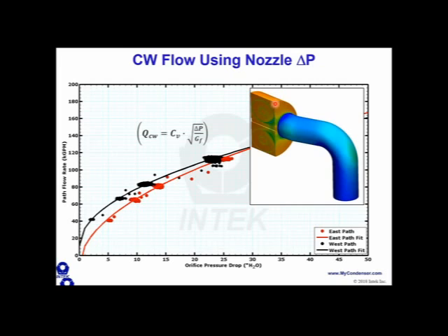So this is what differential producer data would look like. The way we do it is we would recommend doing, again, a very simple CFD model. Just set up the model, predict what pressures you will get at the operating flow rates. If you go down to one pump, you should model that to know what that pressure is going to be, to make sure that you have a range that's acceptable for your flow monitoring requirements. I would recommend just doing a solid model, setting up the flow rates at the different flow regions, the high flow, maybe the 2-pump operation and a 1-pump operation, getting those pressures, finding the optimal positions for the pressure taps to get the largest signal.